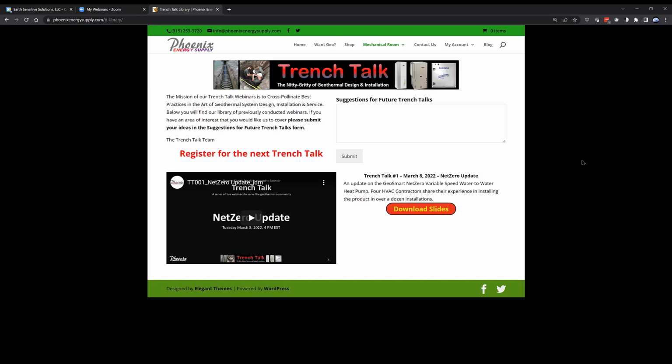And even going to two heat pumps, you really don't have enough diversity to justify variable speed. But certainly going to 3 or 4 or 5 heat pumps, without a doubt, a single variable speed circulating system can be justified.